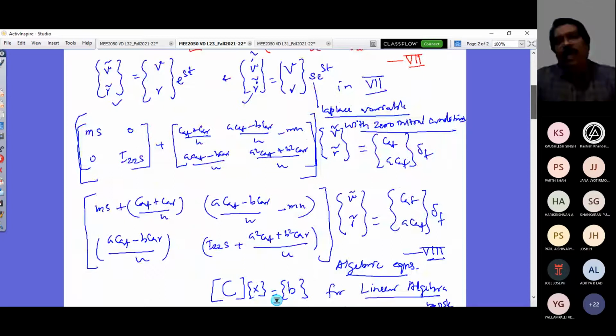So we have looked at how the transfer function of lateral velocity for the given steering angle input can be represented by two ratios of determinants by Cramer's rule. And similarly, we have got it. In this, the denominator polynomial is this delta given by this. So anytime for a bicycle model, you should remember this delta. You have the coefficient for s squared, the coefficient for s, and a constant term. There you define this K3 as the stability factor.